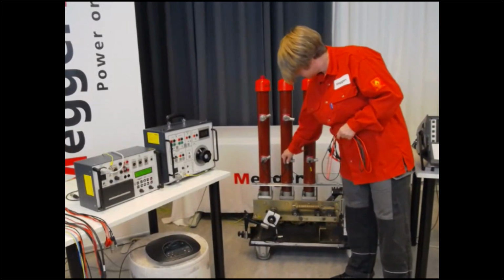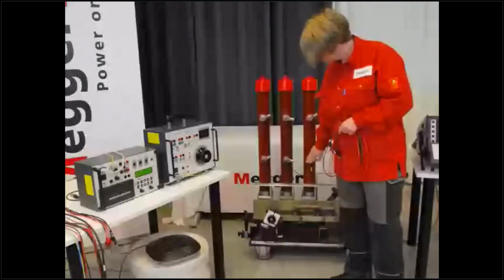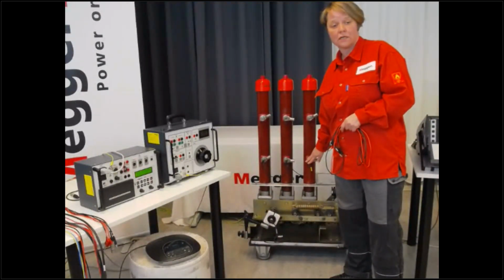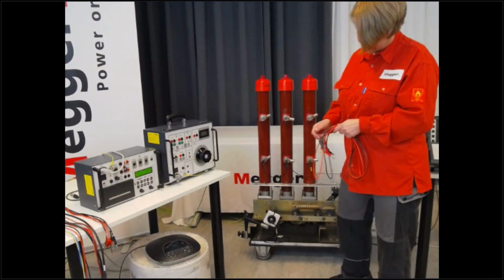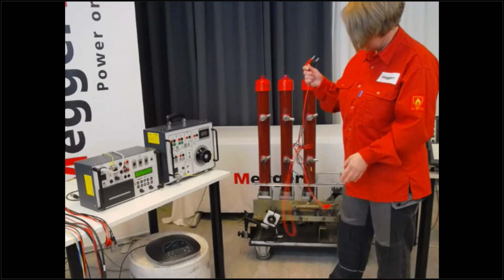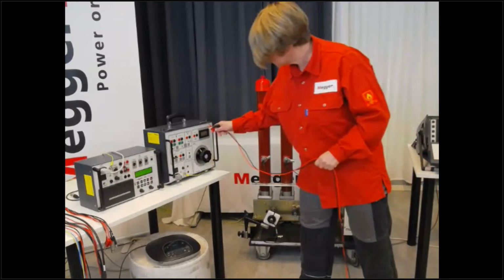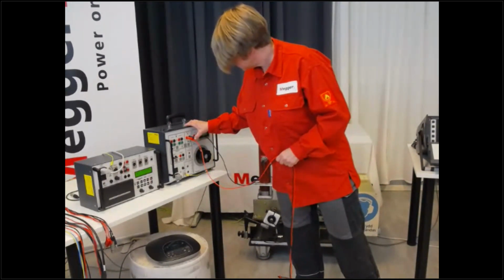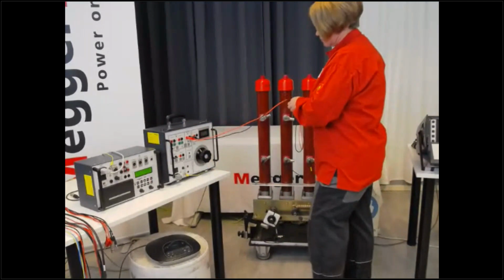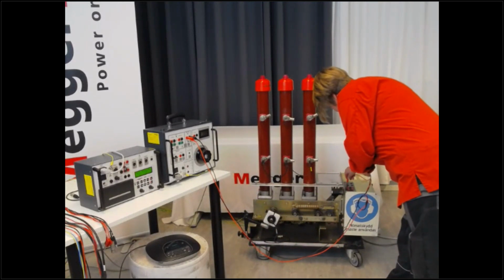On the object here, I have prepared and short circuited one side, because this circuit breaker is not grounded since it's in this workshop environment, and the timing leads here have one common point. So I connect this in advance. The first thing I do is connect the supply for the motor. I'm going to connect to the motor outlet on B10E and to the terminals on the circuit breaker.